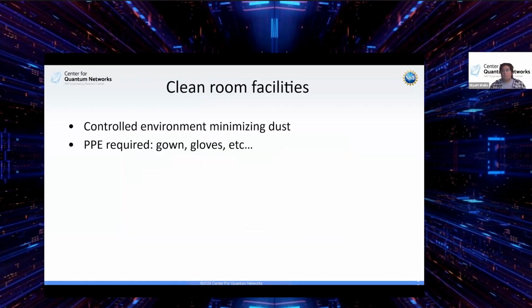So then from here, where do we do these fabrications? What room do we go to? So we go to a clean room, right? And so the whole idea of a clean room, the big goal is how do we minimize dust, dirt, anything from the outside? And so usually that's where there's an immense amount of PPE that you're required to have: gown, gloves, etc. Sometimes some of them require you to have masks on. You've got to have boots on, no dirt allowed. And so these would be the types of places where all the equipment is stored, where all these deposition processes are and things like that.